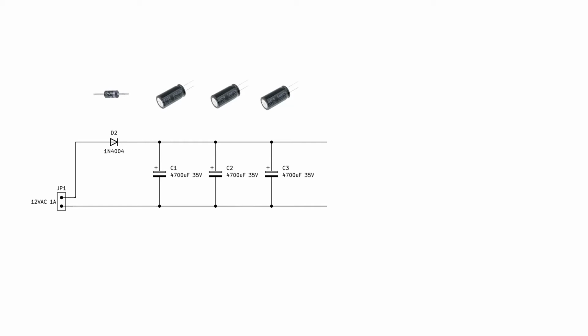And it turns out that we do, however the extra electronics comes in the form of a small semiconductor device, called a voltage regulator. In our case this would be of the type 7812, 78 for positive, 12 for 12 volts. This chip has an input pin, an output pin, and a pin that needs to be connected to the zero level, also referred to as ground. The result is a nice smooth 12 volt signal, capable of delivering 1 amp to our modules.